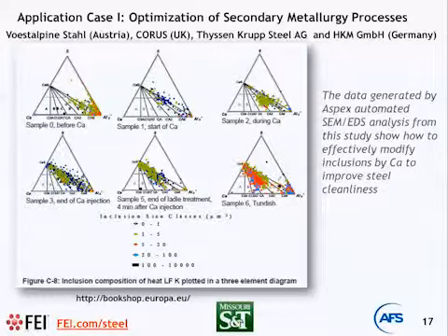Based on that, you can see as the calcium treatment starts and continues, to the end of the treatment in the secondary refining stage, the inclusion populations and sizes really evolve. And in the end, we can also see that after the steel is tapped into the tundish, it shows some reoxidation. It really increases the total population and the size of inclusions. So by doing inclusion analysis, it really helps to directly measure the inclusion evolution,